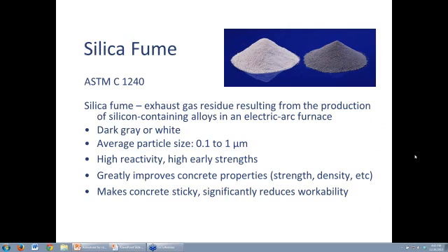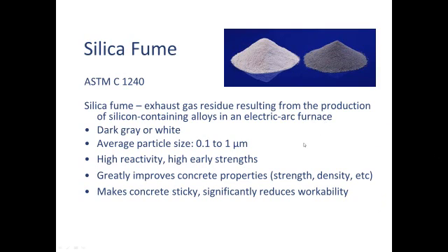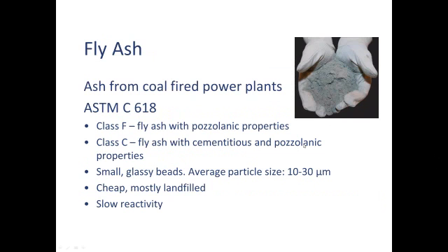There are blends of silica fume and fly ash and slag, and silica fume and fly ash and whatnot. You can go on and drive yourself crazy sourcing and blending all these things till the sun comes down. In the end, what we want is good, strong concrete that we can get out the door quickly. And adding an extra pozzolan doesn't necessarily mean we're going to make extra better concrete. It just means we make more complicated concrete. So I'm going to get off that soapbox and talk about fly ash.